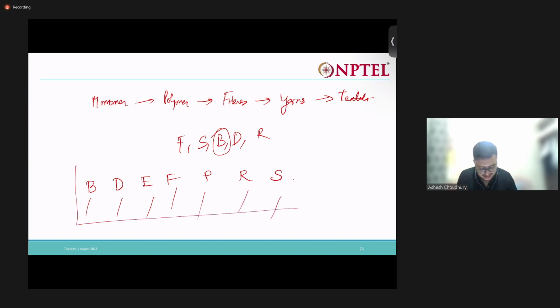You remember all these things and try to correlate which geosynthetic material can be used for which function. All geosynthetic materials cannot be used for all. Geotextile cannot be used as a barrier material, right? You need to use geomembrane for that. So everything should be clear in your mind, which geosynthetic material can be used for which function. As we progress through the course, automatically this will get cleared up one by one, but still these things should be clear from the beginning. Then it will be easier for you.